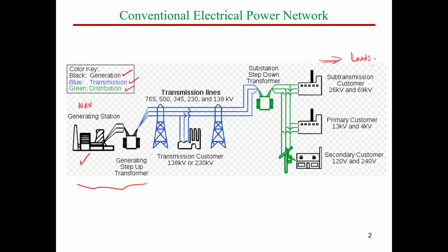How can we transmit our power to customers who need a supply voltage of 110 or 115 or 240 or 220 volt line to line from the 10K? We found that if we start transmitting the power at this voltage level, guys, we will have huge power loss during transmission. We will have some numerical examples on this point, why we use a transformer, because the transformer is going to be one of the topics in our class.